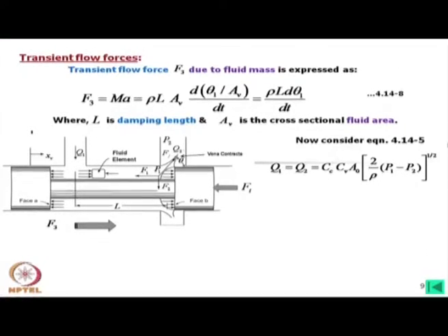So, now we consider again this q1 from that continuity which gives these equations, and then we are obtaining del q1 del t. I have already told that this will be del q1 del t, not theta 1. So, with A 0 equal to W into x v, in reality we have given this displacement. So, if it is opening, our area will be W into x v.